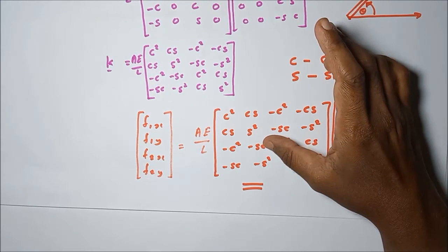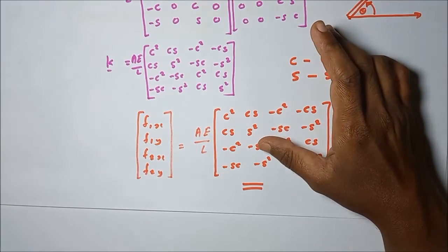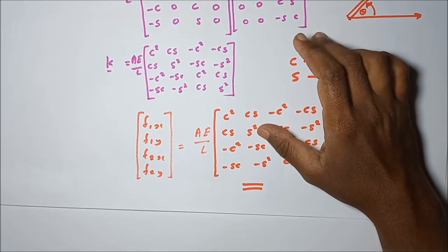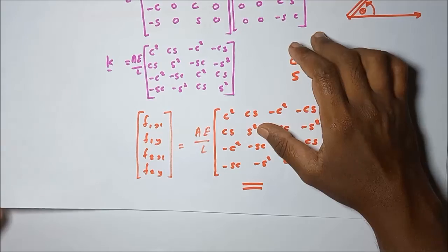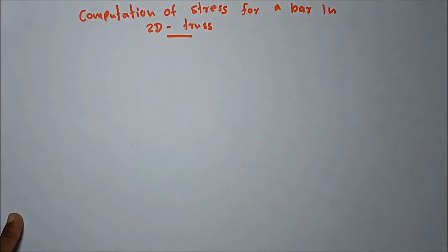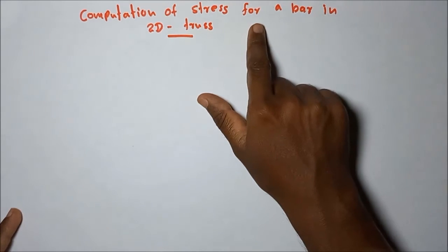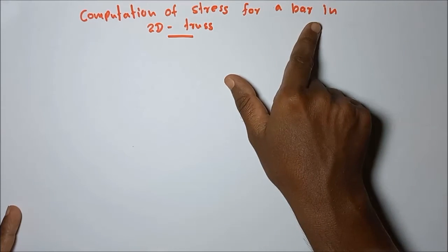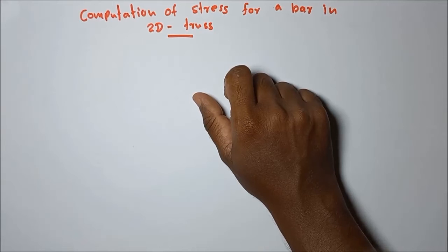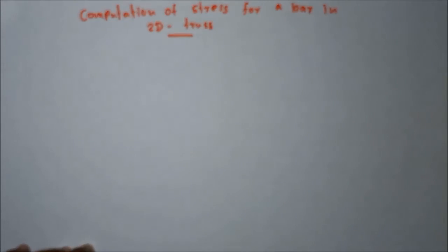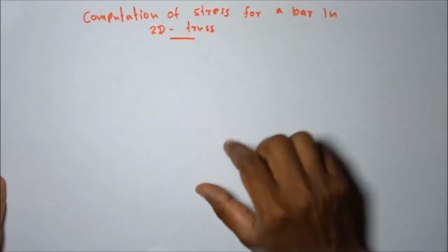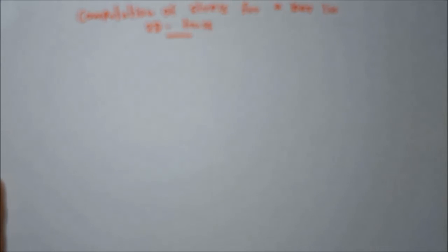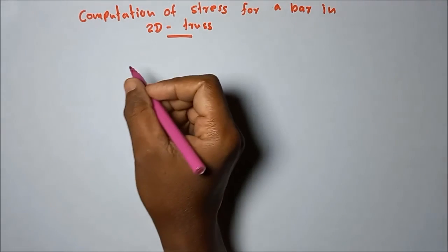Then let's see how to calculate the stresses, the stress developed in each and every bar element in this method. The next theory part is the computation of stress for a bar in two-dimensional trusses. Let's see how to compute the stress developed in a truss bar element on a two-dimensional truss. Let's take a certain bar element.